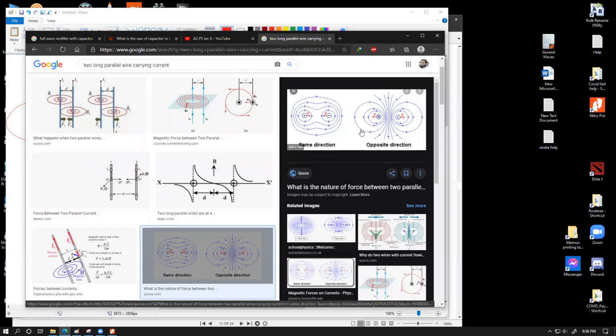But for all the other spaces, the field would be really weak because you can see the field lines are actually becoming really spread apart, because of opposite directional magnetic field. So exclusively for this much space, let's say about 1 centimeter by 1 centimeter, let's say 2 millimeter by 2 millimeter rectangular space within the two wires, you might have a measurable significant magnetic field strength or magnetic flux density. But for everywhere else, that flux density will be really, really weak, almost negligible.